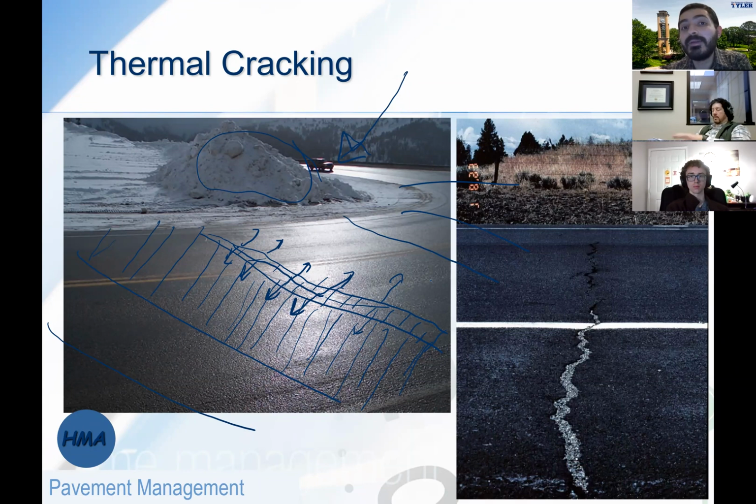Or it can even happen in the middle of the desert. It happens in Arizona, for example, because there is a huge difference between daytime temperature and nighttime. I lived there for 4.5 years. I know how it feels. In the morning, it's about 120. Sometimes we get these days of 120 degrees. This is air temperature, let alone the pavement surface temperature, which reaches somewhere between 135 to 150. And at night of that same day, it can go down to 60 Fahrenheit. That big of a difference is what we call the high temperature gradient.